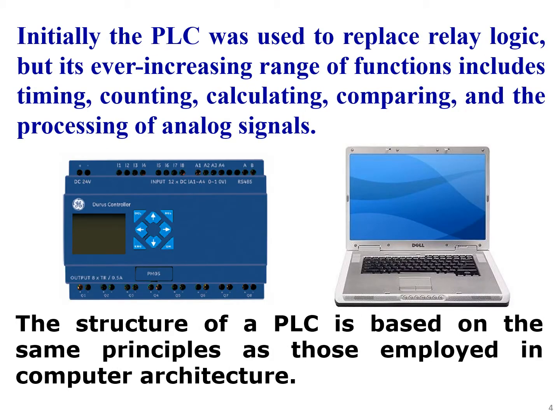Initially, the PLC was used to replace relay logic, but its ever-increasing range of functions includes timing, counting, calculating, comparing, and the process of analog signals. The structure of a PLC is based on the same principles as those employed in computer architecture.